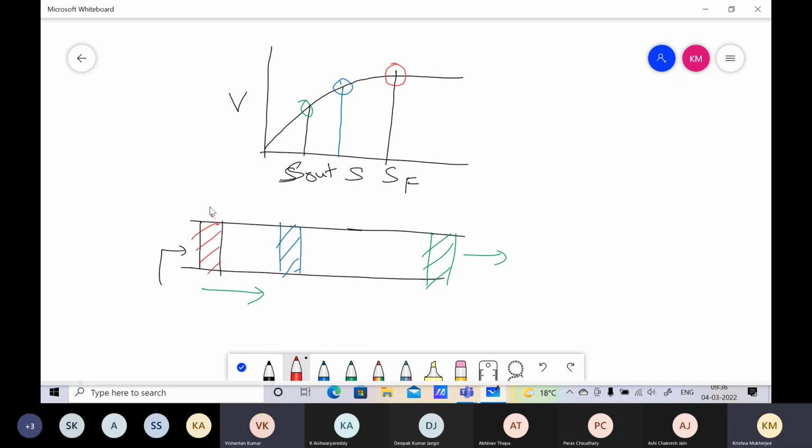And therefore the reaction rate here, Rx, is equal to this. The reaction rate here is equal to this. And the reaction rate here is equal to this. So the reaction rate falls. In the PFR, you will have a reaction rate going down continuously from the maximum to the lowest value. If it goes here, then you are in even bigger trouble.